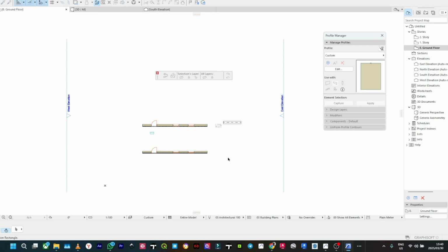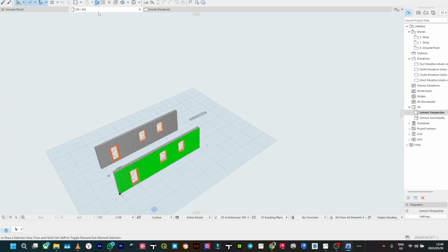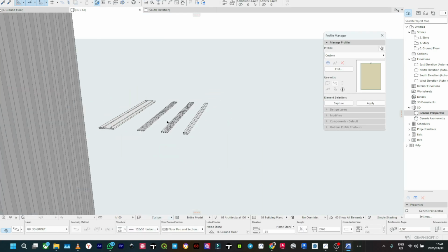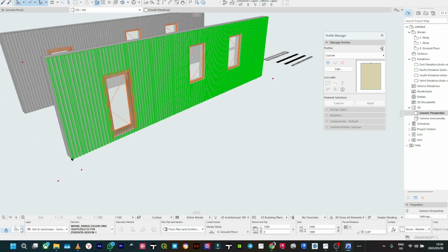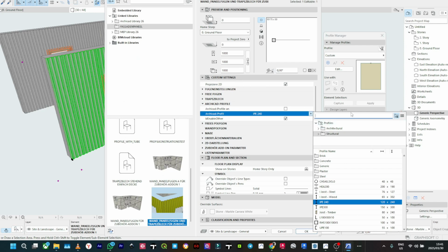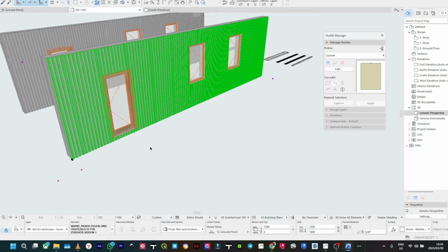So I went to copy beams with custom profiles from another project. I'm gonna paste those there. They are beams. So this one is called 152 by 50 timber. So I'm gonna go in here, go in here, and then look for that one, 152, and go okay.